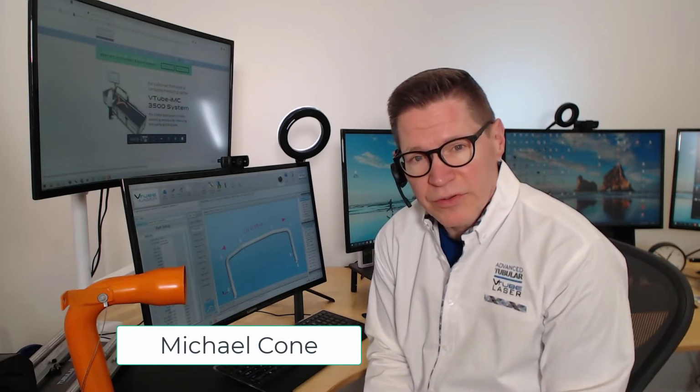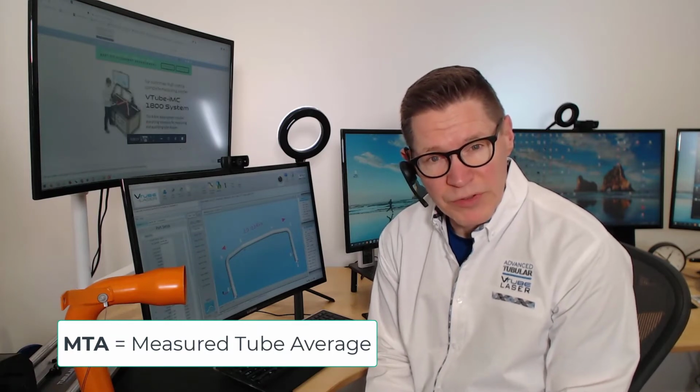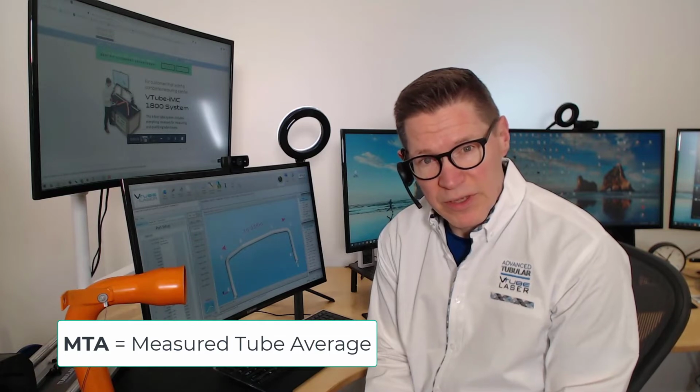And in this video today, I would like to show you how you can use the FARO ScanArm in order to measure and qualify square tubing. So I'm going to have Michelle demonstrate to you how easy it is to measure using what's called our measured tube average process, where we measure along one corner of the tube and then we turn the tube over and we measure on the other corner and we average the two together in order to get to the center of the square profile. So let's go ahead and get started.